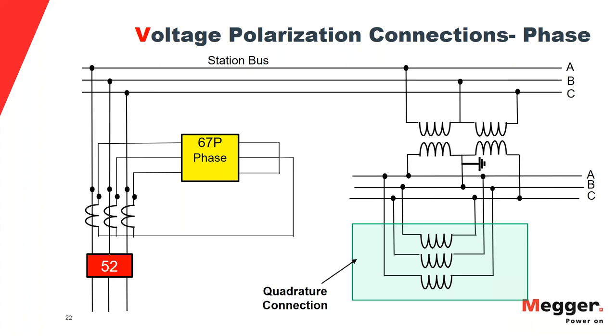Next question is for Danabal as well. Does memory voltage change? It should monitor the voltage prior to fault so as to provide a reference. Is the memory reading and storing the voltage, say, every 5 minutes or so, or how does it work? Yes, memory voltage changes. There are two different types of relays in the market, electromechanical relays and numerical relays.